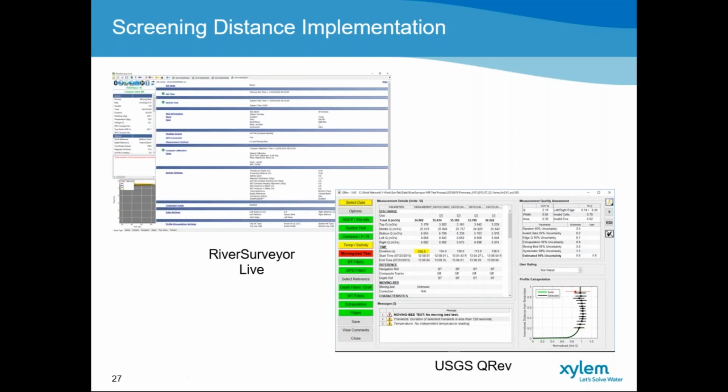So from the research itself, the fact is that ADCP instruments use monostatic transducers that send and receive the signal using the same transducer. So that's a fact, and we know that. We require a blanking distance to remove the ringing effect created because of the transmission of the signal through the transducers.